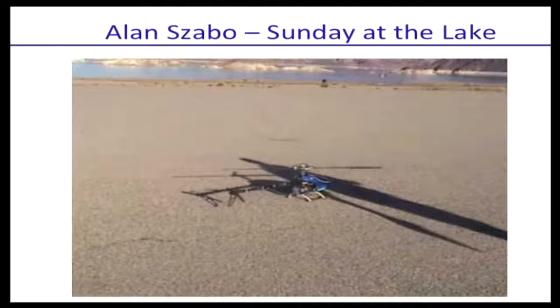Just as people had looked at before, because you're always staying in the same flight regime at all times, you can approximate the helicopter with a linear dynamical system and design a linear control system, let's say an LQR controller. Yes, in practice, you'll have to tune it a little bit, changing the cost of the LQR controller, because your model won't be perfect, and penalize a little more or a little less for control costs, and so forth. But if you do that for a bit, you'll find a good linear feedback controller, and this will work.